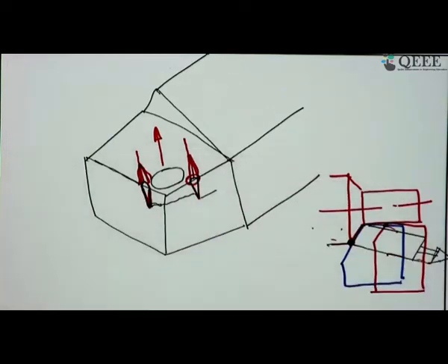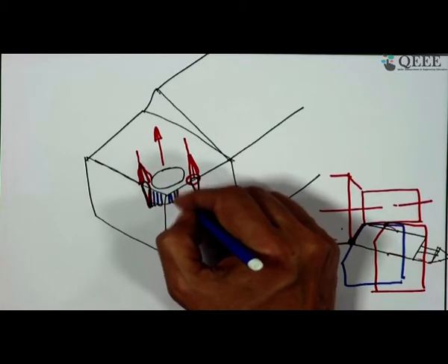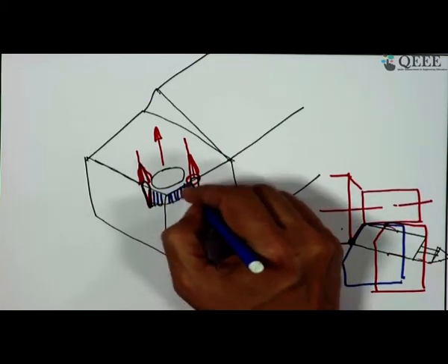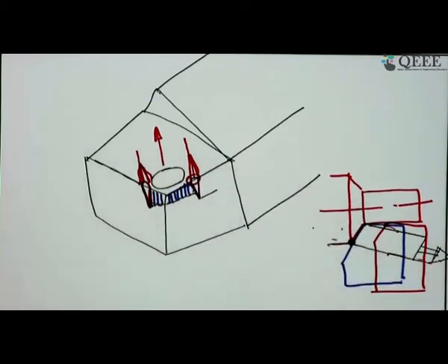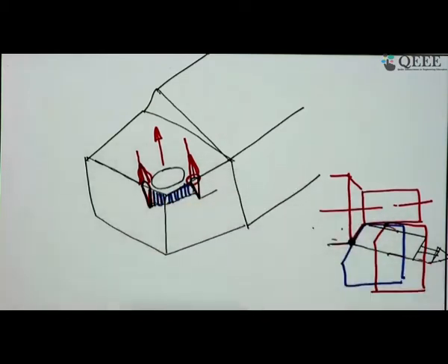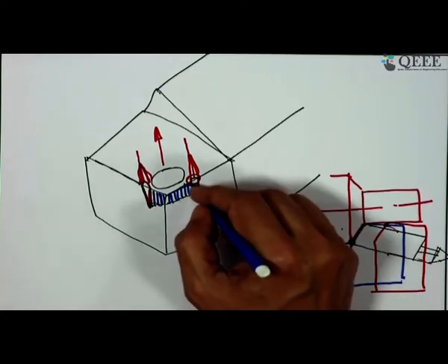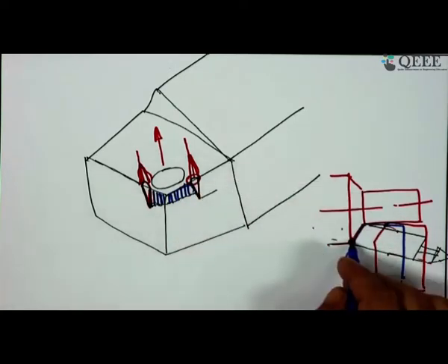the principal flank. So, friend, finally let me tell you this one is the flank wear on the principal flank, this side is the flank wear on the auxiliary side, and on the principal flank you have a notch at the border line.